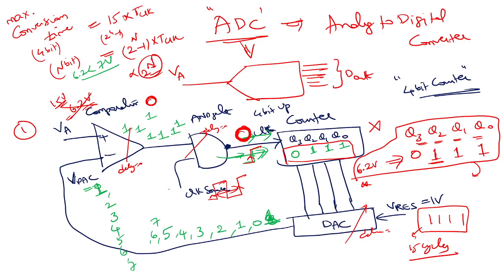And also, you look at this comparator, right? Correct. So let's say, for example, if I take this value as 6.03 volt, and here this is 6 volt. If it is ideal comparator, then output will be 1. If it is non-ideal, depending on the characteristics of the comparator, output may become 0 also.